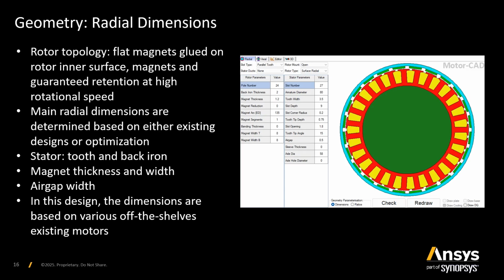So if we go further, we can look specifically at the rotor details. The template default configuration for this type of machine will typically make use of arc-shaped magnets. In reality, for this machine, we're dealing with rectangular magnets. They're easier to manufacture, easier to magnetize, and they can be placed on a flat area of the inner surface of the rotor.